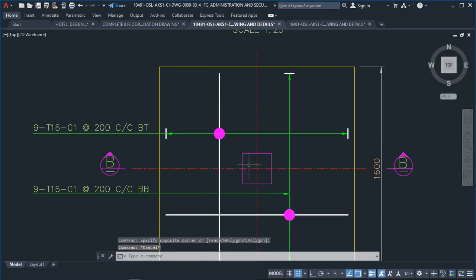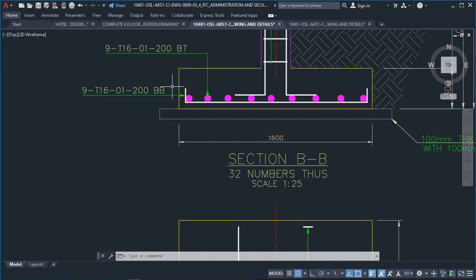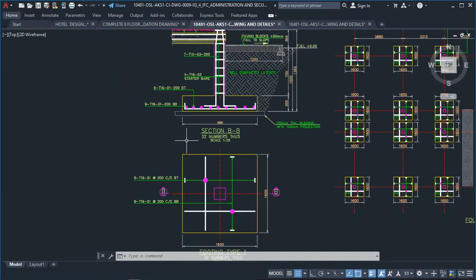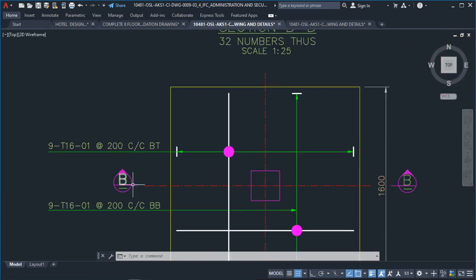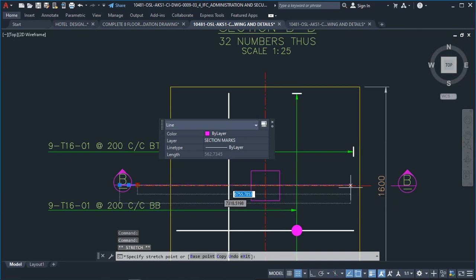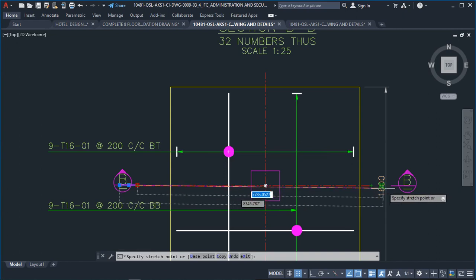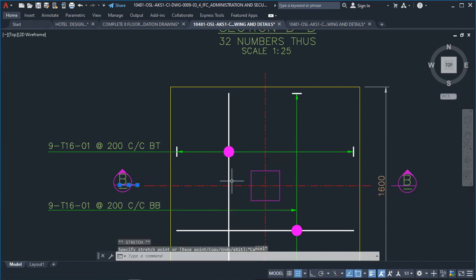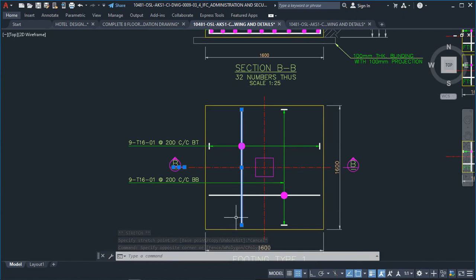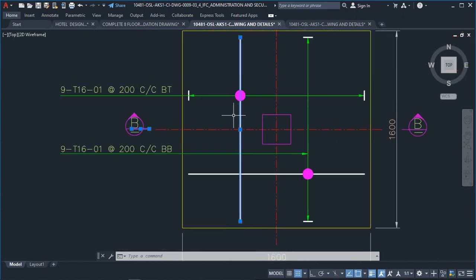Now, one must carry the other before they can intertwine. So if we cut this section on this side, this section is trying to cut this reinforcement. So this section cuts this reinforcement. So when you look at this reinforcement on this side, you will see this one as if it's a circle because it has been cut into two. So looking from this side, you'll be seeing this reinforcement as if it's a circle.